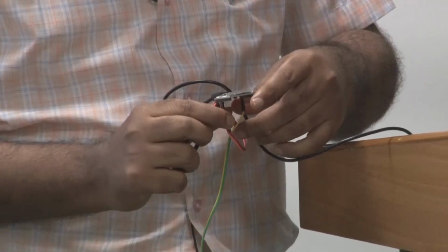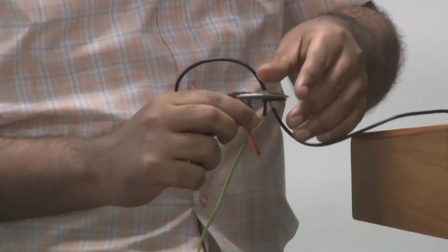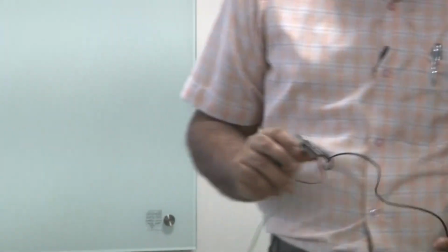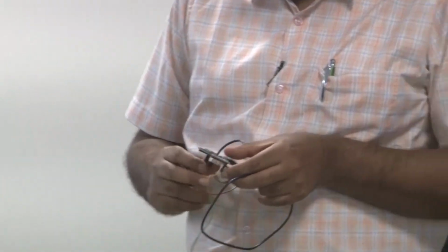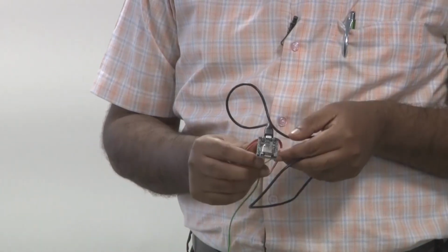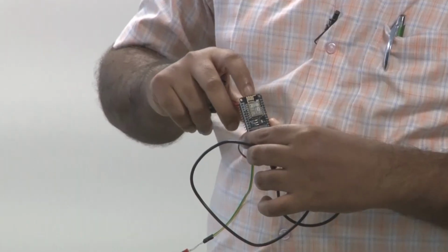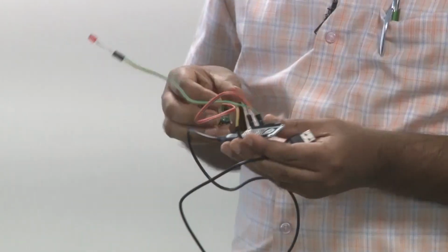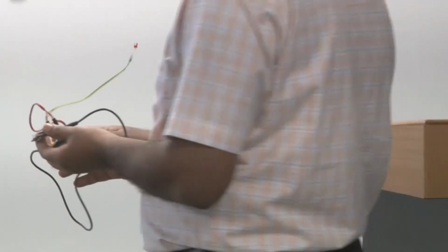Now, let us look at how to get it to work. I am getting it to work on an ESP8266 board, which is different from the ESP32 board that you saw here. It has a fewer number of GPIO pins, general purpose input output pins, but it works pretty much on the same concept, and you can see here that is its wireless antenna. All I need to do is to connect the circuit and write the code and also install this board.